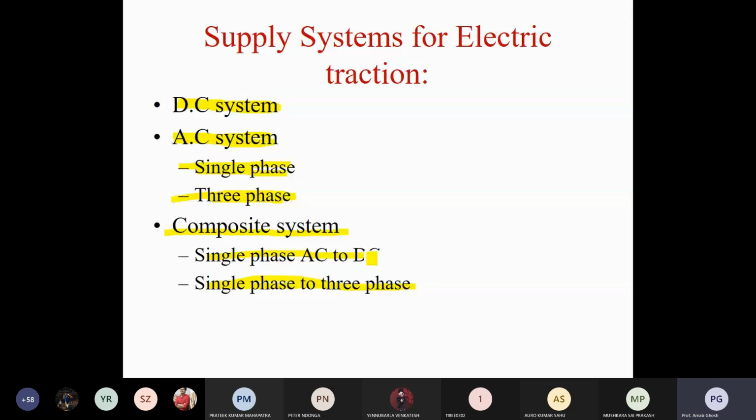But in case of DC to AC configurations, you are using an inverter. If there is an AC configuration, you can use cycloconverter drives. Why cycloconverter drives? Basically, with inverter and cycloconverter, the basic advantage is that you can change the frequency. You can also use a three phase AC voltage controller, but you cannot change the frequency. But in V/f control, voltage and frequency both should be changed within tolerable limits. That's why frequency control is important.